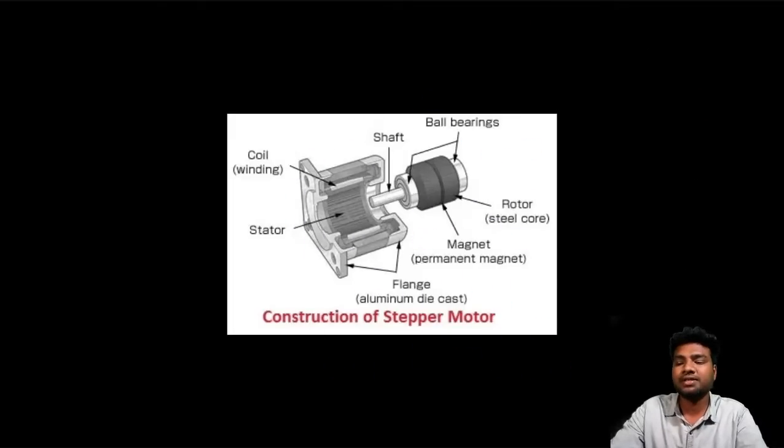So to change steps, we know we have to change the step, and only then can we rotate the shaft, like the output shaft of a stepper motor. If you want it to rotate, we have to change the step. Changing the step means, in RTL in the Verilog code, we have to use a counter. Based on the counter value, I can change the step.